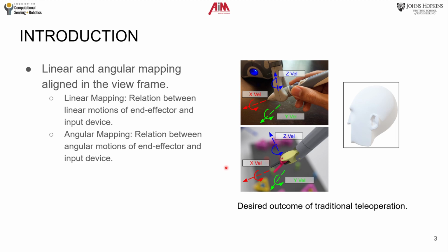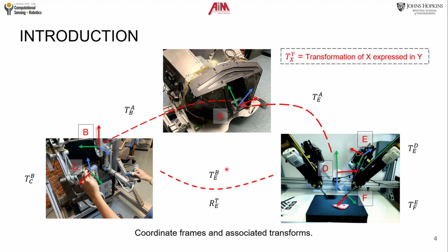It is also desirable for certain applications to have force feedback on the input devices that results from the remote robot interacting with the environment. Since several intermediate components are involved in the teleoperation scheme, achieving hand-eye calibrated motion requires the knowledge of the hierarchy of individual components and the proper coordinate frame assignment to each component.